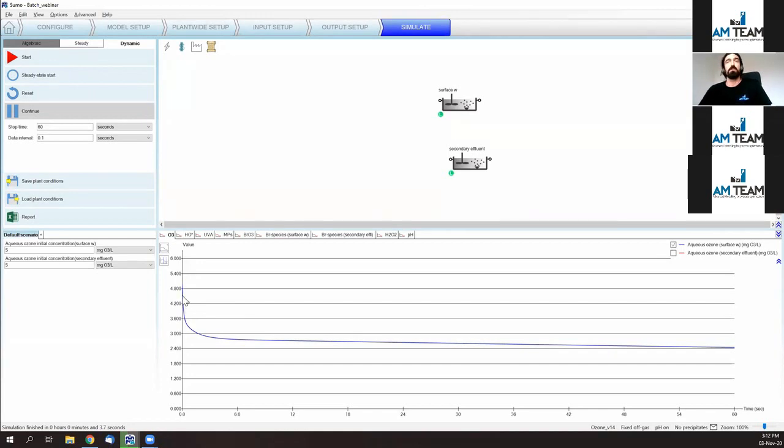And you can still observe a first very fast reaction of ozone, where the concentration drops very, very fast downwards to lowest concentrations, and then it slows down and reacts slower and slower. This is the consequence of ozone reacting with UVA, so the fraction of organics. So it's a matter of describing organics in solution, and the UVA fraction is depleted very fast initially, because the easily breakable organic molecules can be degraded very fast, and then you have the die-hard part of the organics, which takes a bit longer.